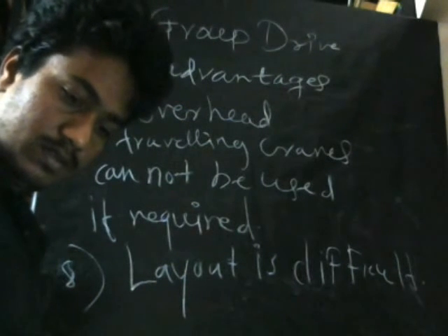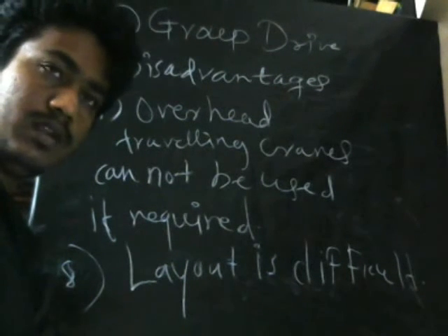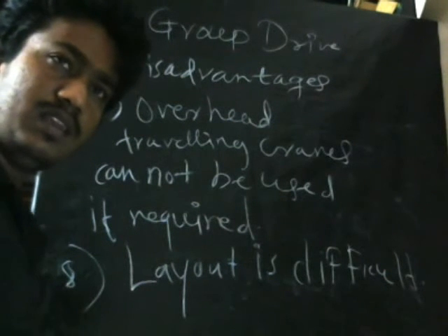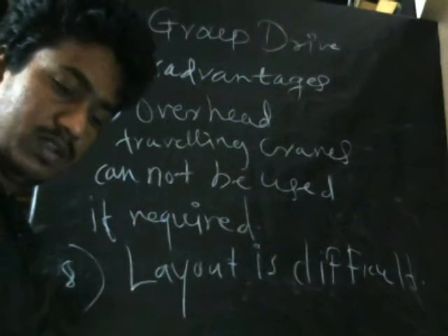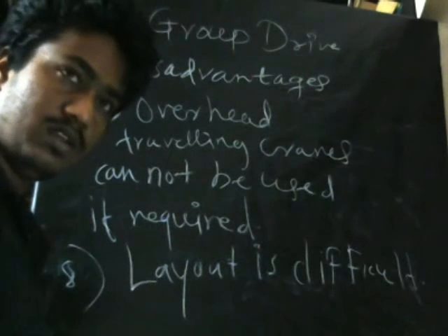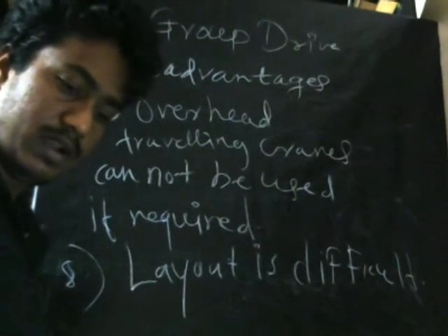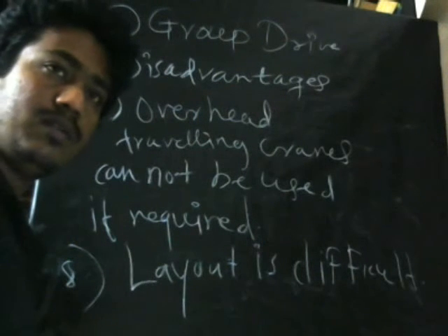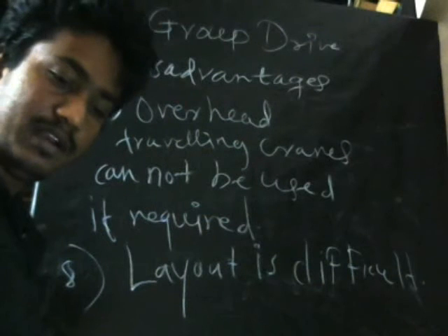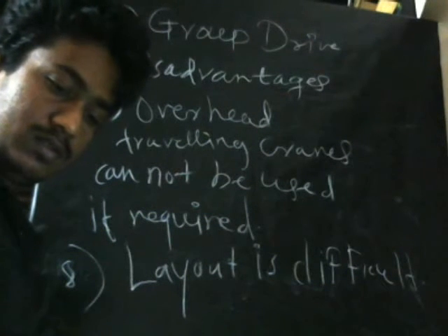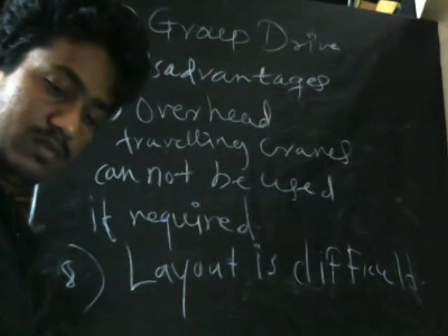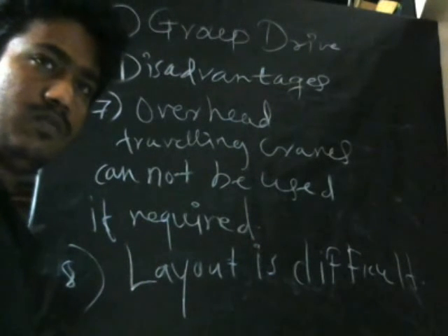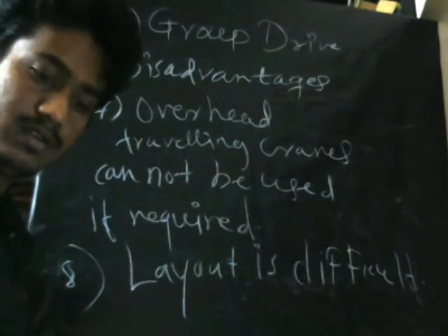Okay, and then to the machine shaft. The main thing here is that we are using belt drive. That is the point of consideration and concentration, that we are using belt drives and pulleys. The main shaft gets power from the electrical motor by belt drive or chain drive, and the motor can be mounted on the floor or overhead.